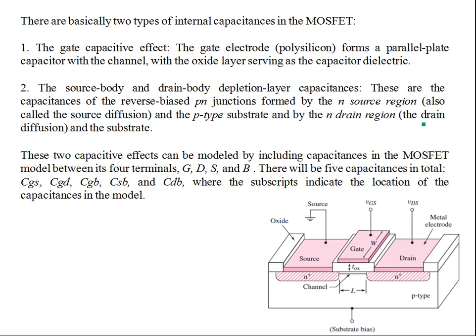Now, if you recall our earlier discussion of MOSFET construction, it's primarily a four-terminal device, with the substrate and the source usually tied together, and they are both connected to the most negative point, which is the common of the circuit. So you don't see the bulk or substrate terminal. Then you have the VGS, so it's basically a three-terminal device: the source, the gate, and the drain terminal.